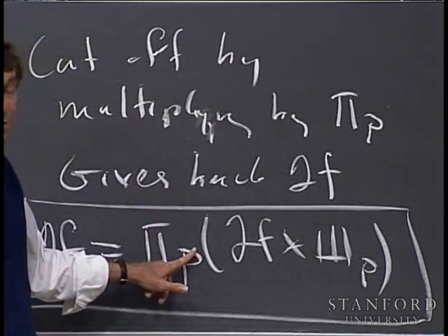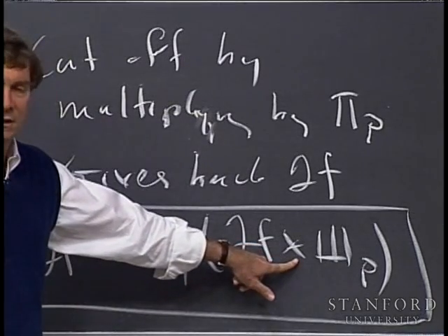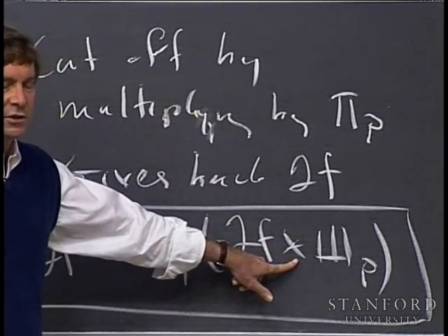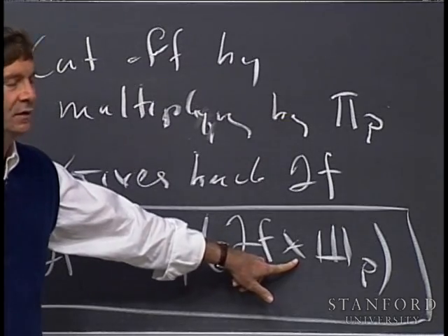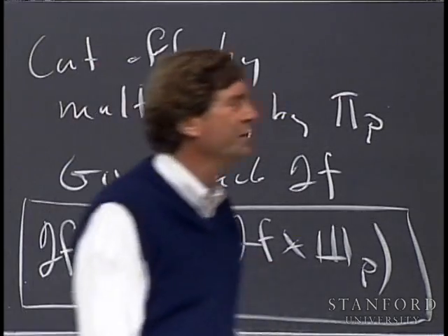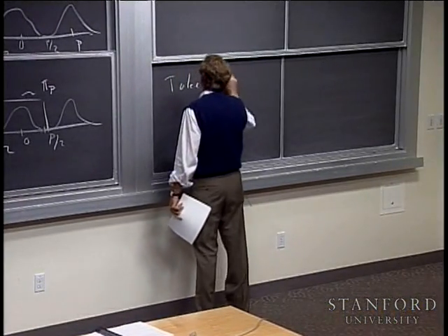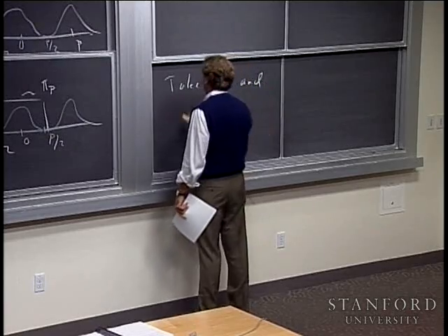It's multiplication here, so in the inverse Fourier transform, that's going to turn that multiplication into convolution. It's convolution in here. When you take the inverse Fourier transform, it's going to turn that into multiplication. Sampling comes from this part, and the sinc function comes from this part, and you turn the crank, and this is what you get.